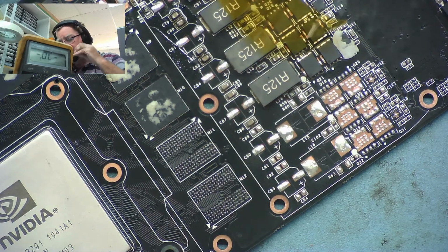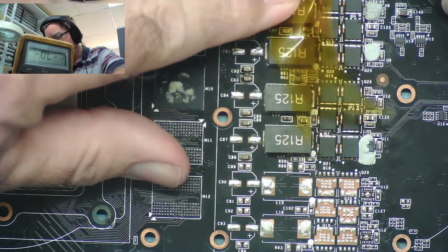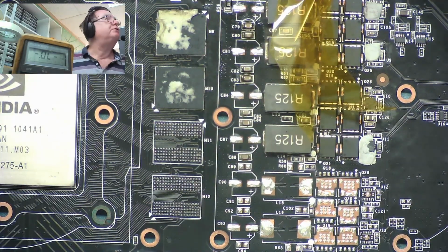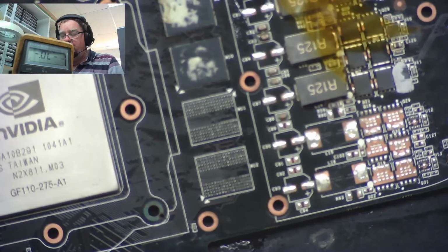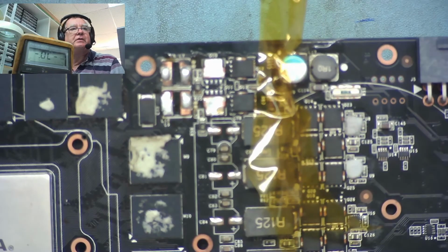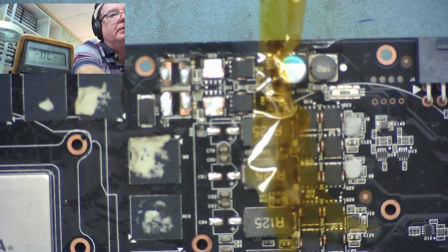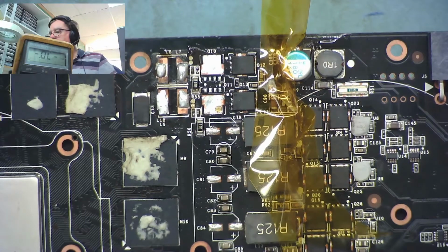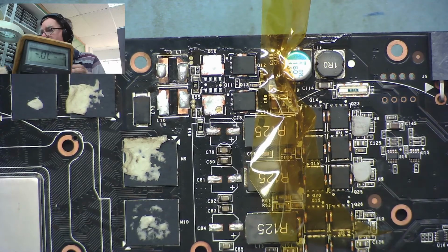A bit more Kapton. There's a little resistor or something down there. I certainly want to keep the heat out of the capacitor, for sure. Otherwise I'd be tempted to actually desolder that capacitor. But no, I think we can get in now, and we can probably desolder these MOSFETs without too much drama. Okay, where's my little metal plate? I'm not going to bother trying to get leaded solder on them because there's a big tab underneath these things anyway. Okay, let's just set the focus for you. Okay, that should do. Tweezers, check. Hot air, check. Let's go for it.